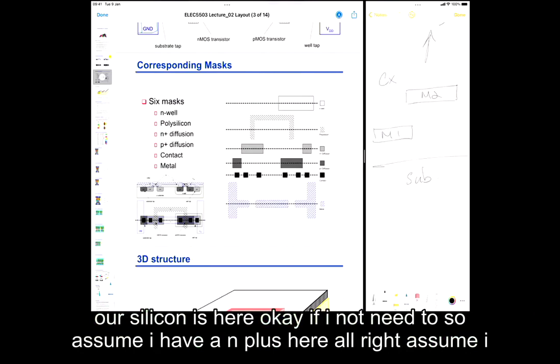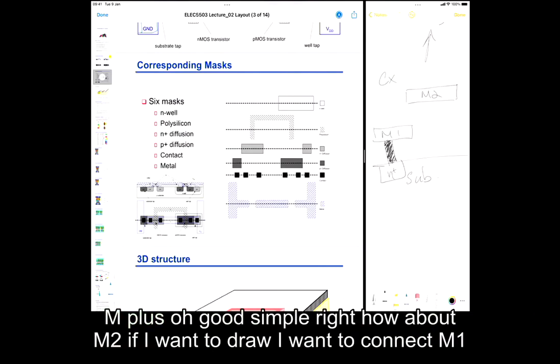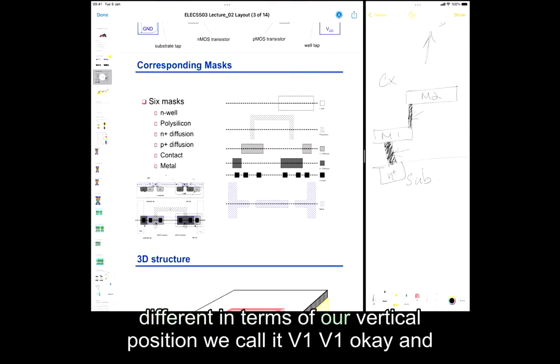Assume I have a N+ here. Assume I need to connect N+ to M1, then I need to draw a contact. Contact is usually done by copper. So I have a hole, and then I fill in copper, so that my metal 1 can connect to my N+. All good? Simple, right? How about M2? If I want to connect M1 to my M2, I need another, well, we don't call it contact, because if we call it contact, then this layer and this layer will be the same. So since they are different in terms of vertical position, we call it V1.